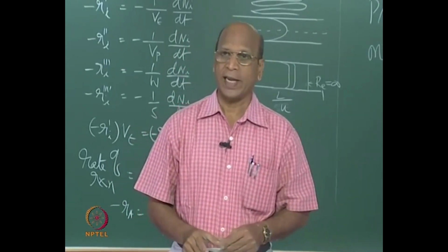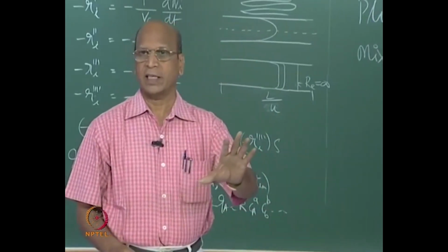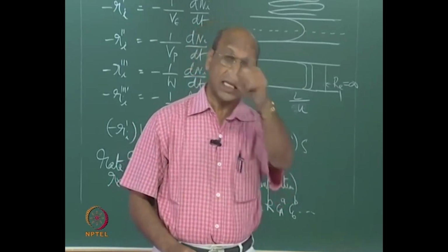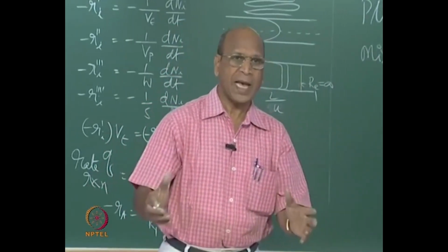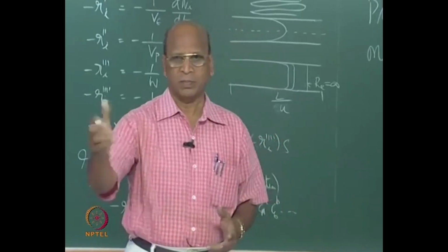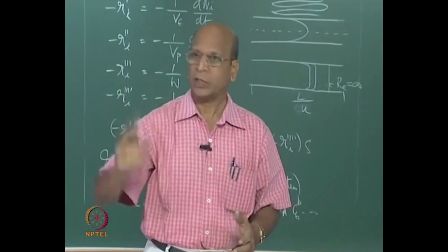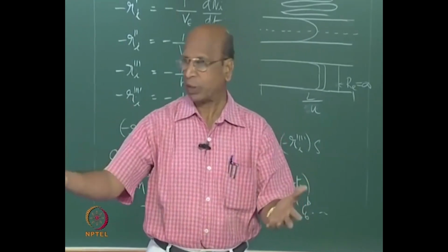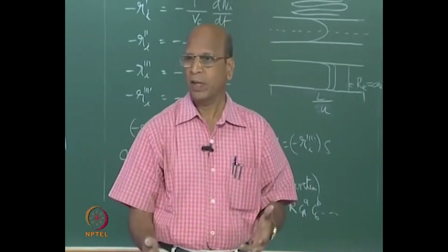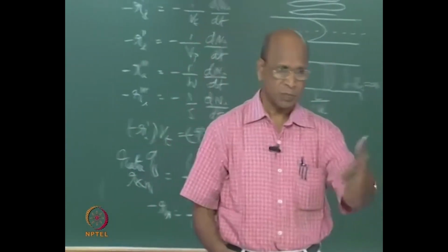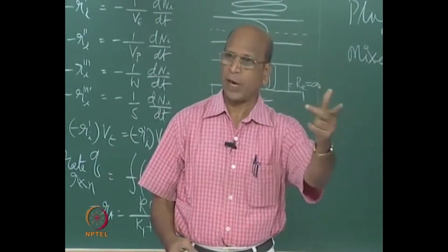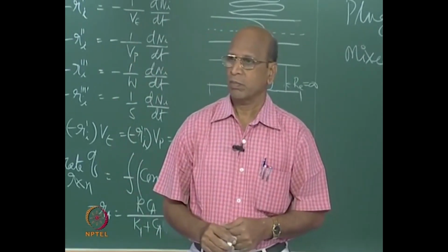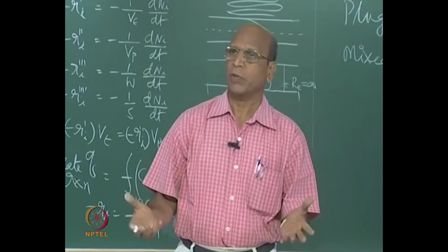So, that is the reason why whenever you have exothermic reactions, we go for mixed flow, even for very highly exothermic gas phase reactions, because there I do not worry about the timing, I do not worry about conversion, I worry about the heat, which may explode after some time if the heat is building up, or when the hot spot reaches the flash point and then everything may burn. So, safety is very important. That is correct, no? Definitely safety is very important.